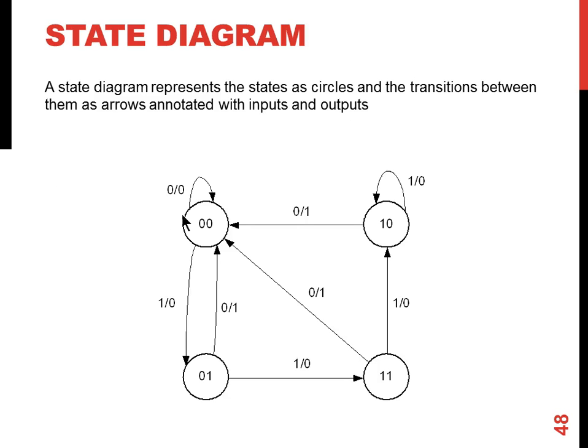Here now we have a four-state machine FSM. There are four states. It is binary encoded. So the states are represented as 00, 01, 10, and 11. Depending on the input combination, this is my reset state, so it will always go back. This is the idle state or a reset state. Initially, the machine will enter this state. From this state, it will go to one of the other states depending on the input combinations.